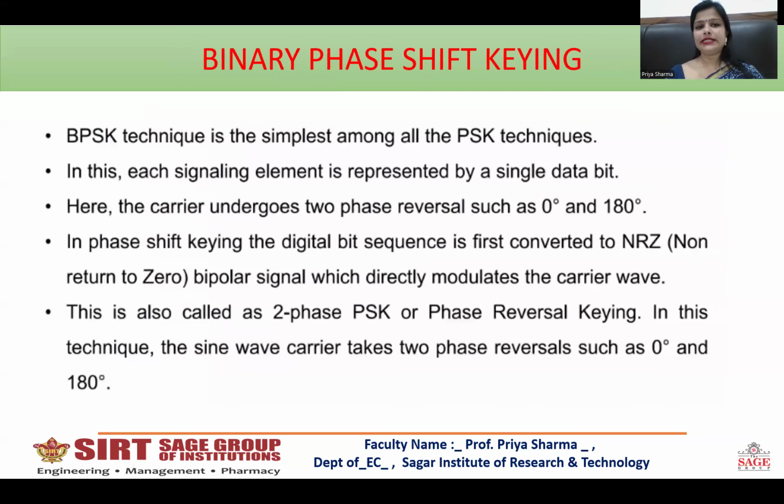Now coming to the BPSK, that is binary phase shift keying. BPSK technique is the simplest among all the phase shift keying techniques. In this, each signaling element is represented by a single data bit. Here, the carrier undergoes two phase reversals, such as 0 degree and 180 degree. In phase shift keying, the digital bit sequence is first converted to a non-return to zero bipolar signal, which directly modulates the carrier wave. This is called a two-phase PSK or phase reversal keying. In this technique, the sine wave carrier takes two phase reversals such as 0 degree and 180 degree.